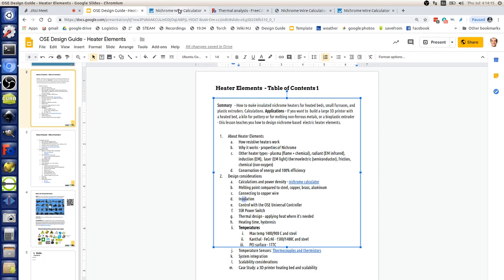That's a lot. So typically, they start glowing white hot or red hot. A normal steel wire would just burn out over time. It would rust and oxidize and go away. The special property of nickel and chromium is that they do not oxidize at the high temperatures. But you still have to insulate them. So in the case of our 3D printed bed, we insulate them and we control them through the Arduino controller with a solid state relay power switch.